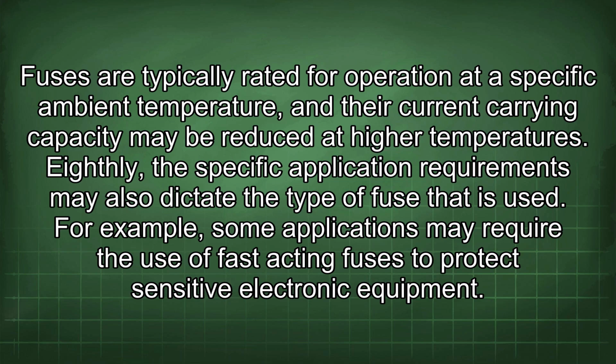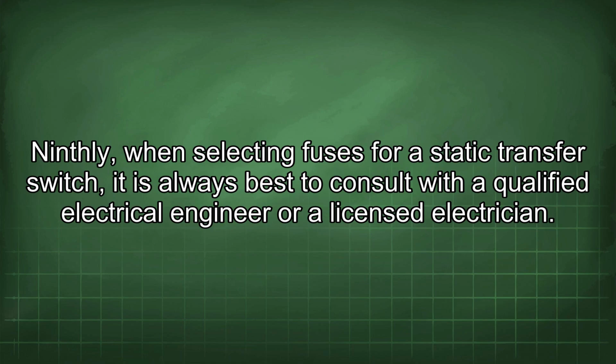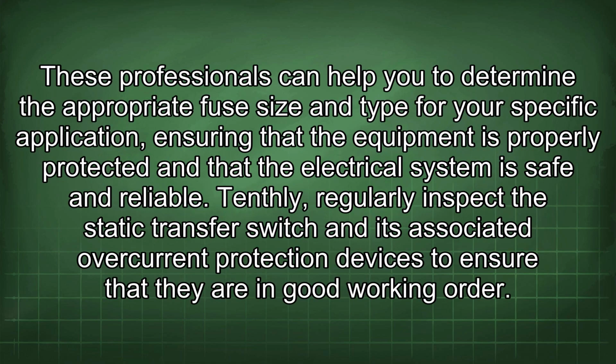For example, some applications may require the use of fast-acting fuses to protect sensitive electronic equipment. Ninthly, when selecting fuses for a static transfer switch, it is always best to consult with a qualified electrical engineer or a licensed electrician. These professionals can help you to determine the appropriate fuse size and type for your specific application, ensuring that the equipment is properly protected and that the electrical system is safe and reliable.